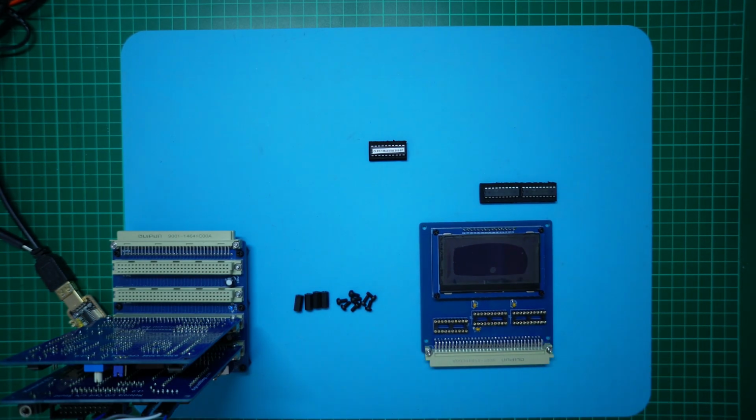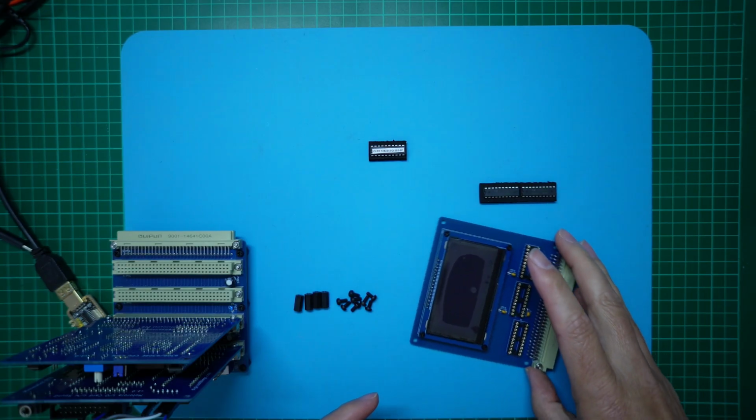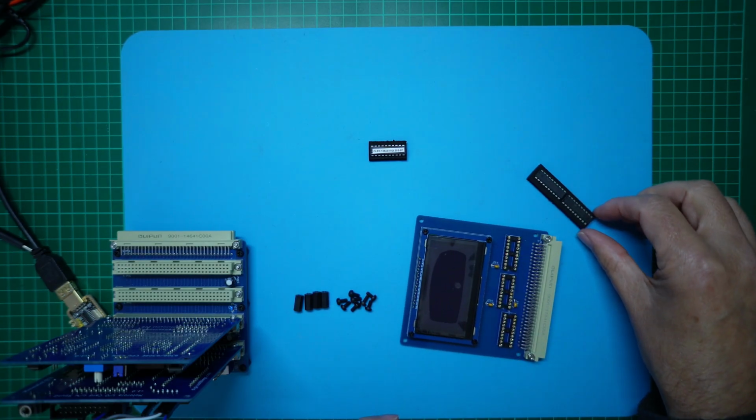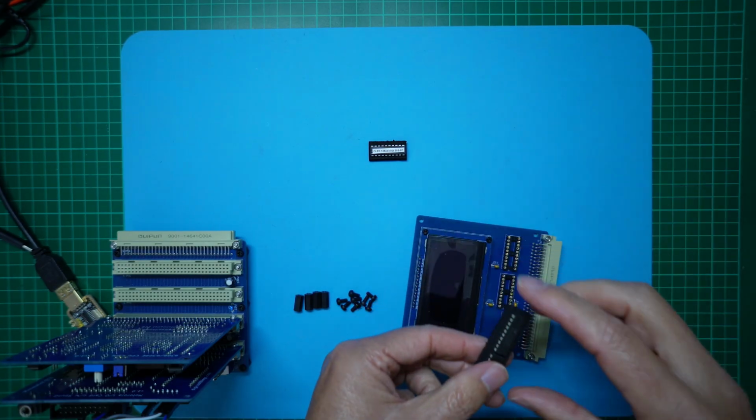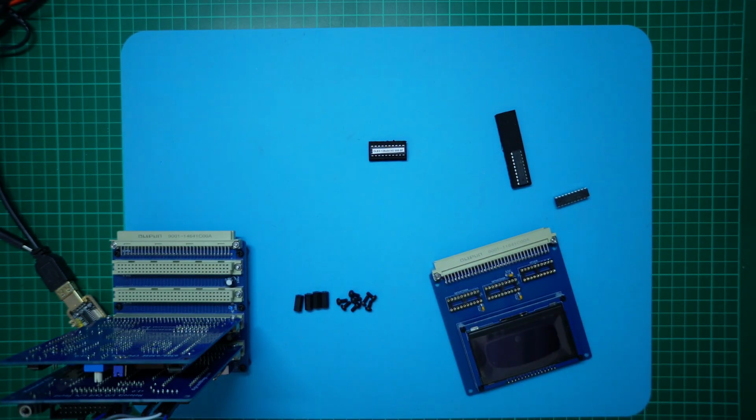Okay, with the OLED panel mounted, I'll now fit the 2 dual inline ICs that provide the bus buffering. That's 74HCT245s. So I'll just grab my pin straightener.